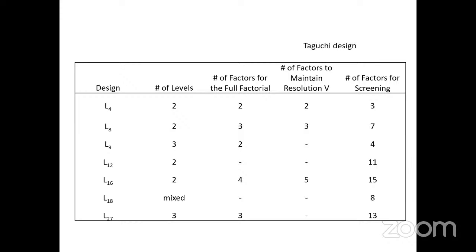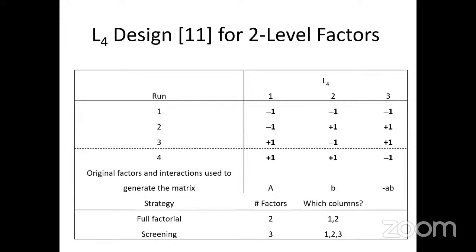Screening designs are also called linear designs because you do only 2 levels, right? It is like temperature 50 degrees, 60 degrees, pH say 5 and 6. Okay, 2 levels. Time could be 80 minutes, 90 minutes, 2 levels. So that's why they are called linear designs. We can also have non-linear designs if we do experiments at 3 levels. 3 levels means you can fit a quadratic relation. You can even have 5-level designs, called central composite designs. Those are called non-linear designs or quadratic designs and so on, whereas these are all called linear designs. So these are all Taguchi designs.